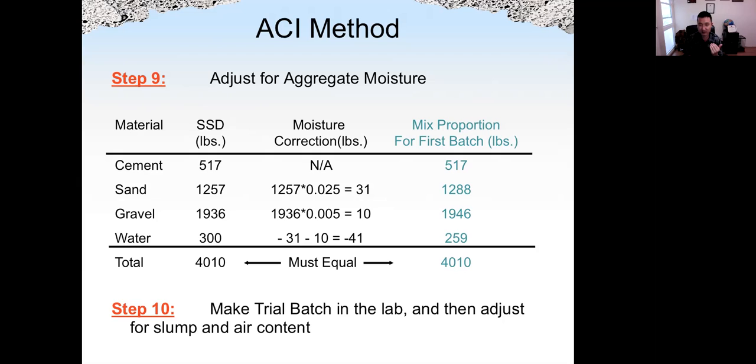The moisture content could also be negative. Negative means the aggregate is air dry, drier than SSD. So we're going to adjust the moisture accordingly.